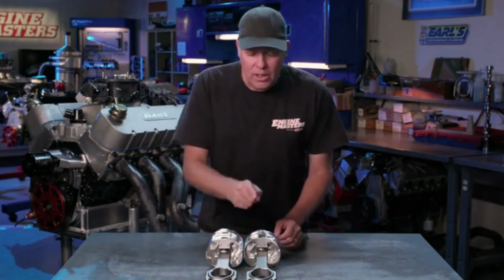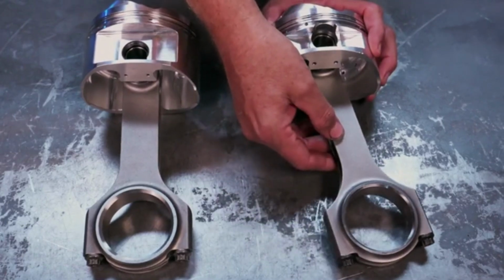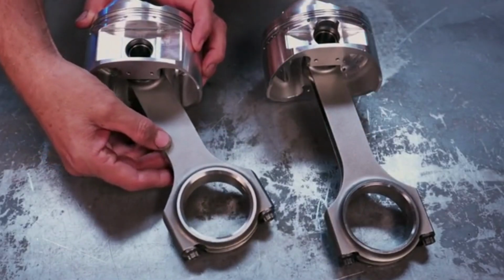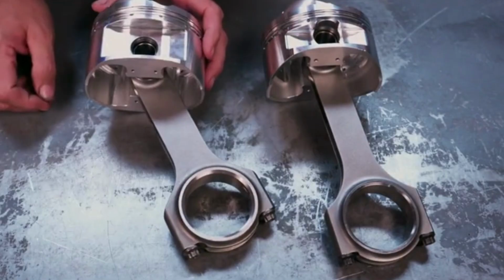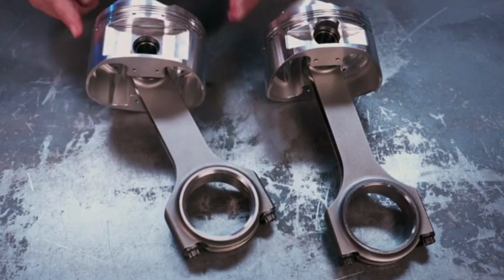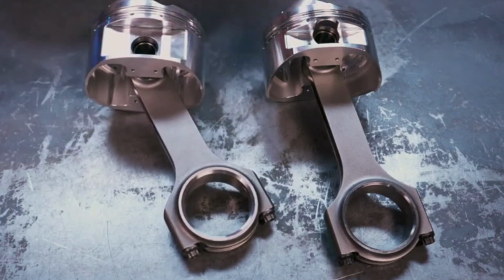And here's another thing that's an effect of long versus short rods, and I'm gonna exaggerate it here on the table. Let's imagine that these pistons and rods are both in an engine with the same amount of crankshaft rotation. With the long rod, the angularity from the piston to the rod might be about like that. With the short rod, it is much more extreme, something like that. And therefore, the short rod causes more side loading on the piston. This rod is actually shoving the piston more this way into the cylinder wall, which can lead to friction problems and mostly more bore wear.